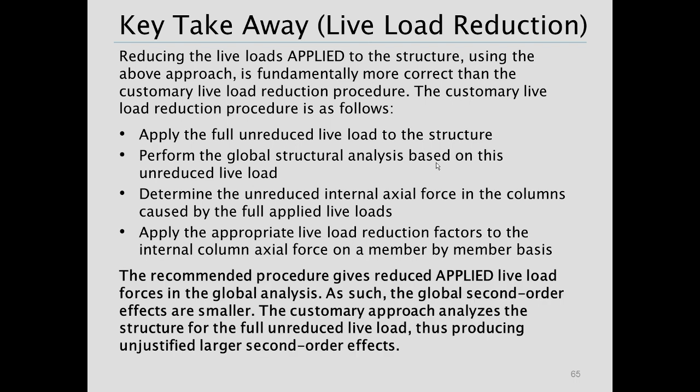What I've just shown you basically gives you the same reduced live load forces in the members, but we are performing the calculations in a way that reduces the applied live load forces in the global analysis, and by doing so, the global second order effects are going to be reduced. Our customary approach analyzes the structure filled to the gills with unreduced live load, and so we tend to produce what you could say is an unjustified larger second order effect.